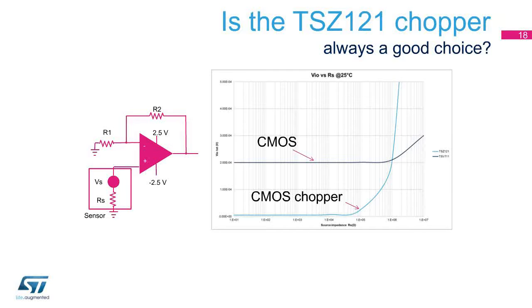The dynamic behavior of these switches induces a charge injection current on the input terminals of the amplifier. The charge injection current has a DC path to ground through the resistors seen at the input terminals of the amplifier. Higher input impedance causes an apparent shift in the input bias current of the amplifier, resulting in a higher input bias current than conventional CMOS op-amps.